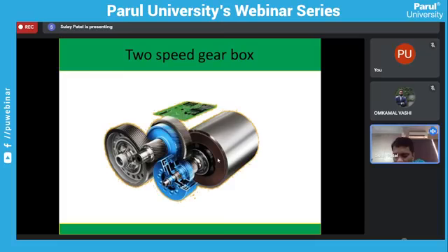By utilizing a multi-speed gearbox, they are going to achieve a reduction in the size of the battery as well as downsizing of the electric motor, and they are searching for how to increase the range of the vehicle with the downsizing of battery size. So all the research is going on in this scenario for the multi-speed gearbox.